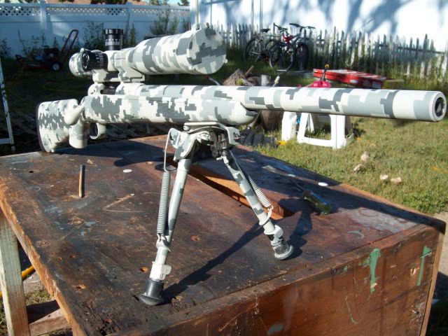They can change shape with temperature, and if you have barrel tension underneath on a plastic stock, and I'm talking about the injection molded stocks, which are a totally different thing from a Macmillan fiberglass stock, a lot of times you'll have a point of tension forward underneath the barrel, and with temperature, the nature of the plastic changes. It becomes more plastic, and by plastic I mean plasticity, the ability of that stuff to deform.